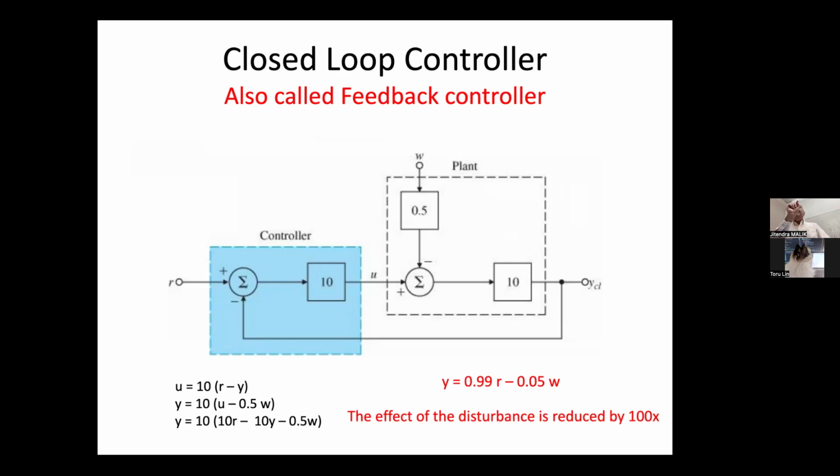So you didn't get exactly your 55 miles per hour, but 54.1 or 54.2. Suppose there was no grade, the road was flat, you would still pay that penalty. So there is a steady state error here. You're not achieving Y equals R, you're achieving 0.99R, but that's a small loss.